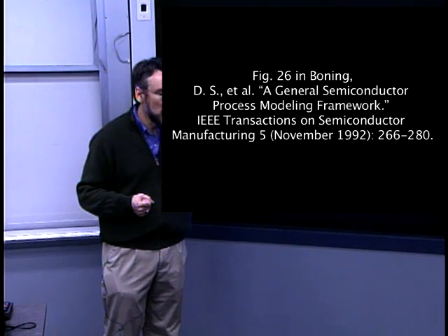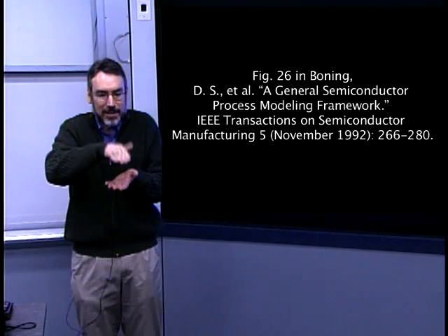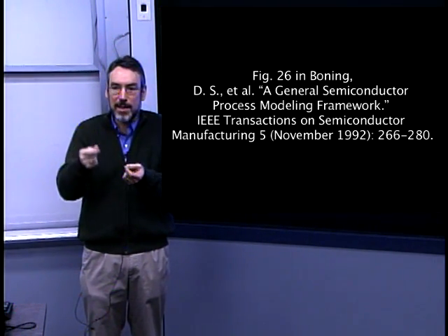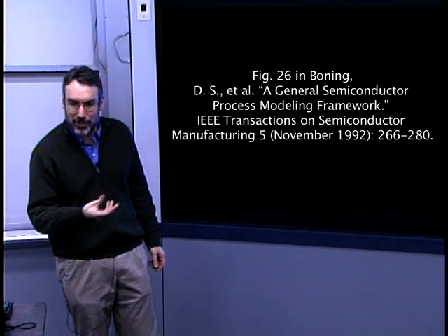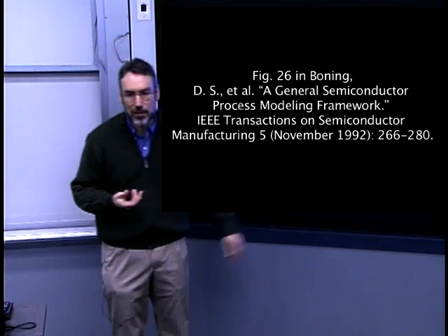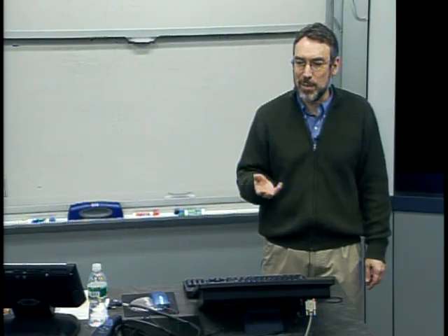And then we get changes in many of these wafer states. Many of these are desirable. We saw the change in the wafer state in terms of the geometry, as well as things like doping processes that change the conductivity of the silicon layers. But we also often have, as side effects, changes in the state of the equipment. And this turns out to be a big deal in much of semiconductor control.